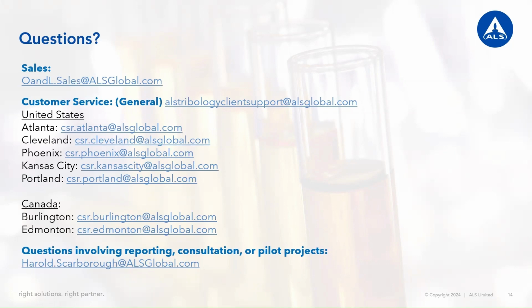There are several studies that I personally have done for clients. Usually what we'll do is select a number of units and monitor their TBN value over a shortened drain interval, their current drain interval, and a longer drain interval, just to see how that value reacts to being extended out.